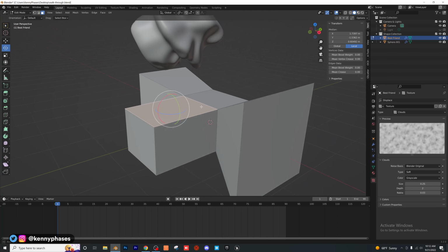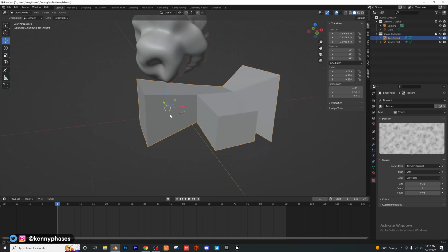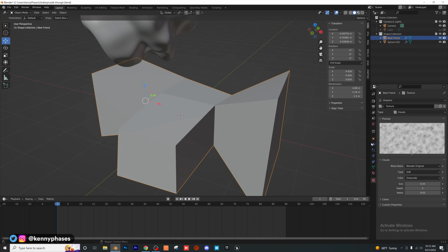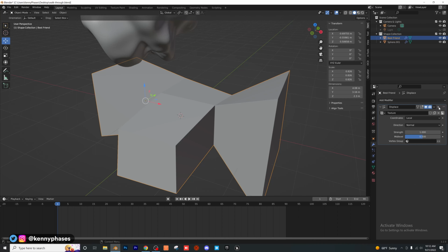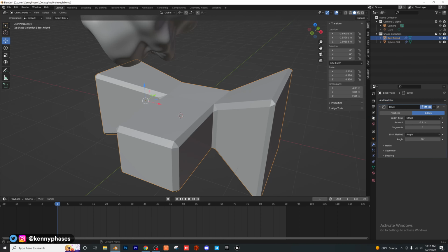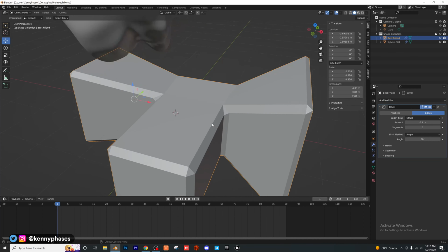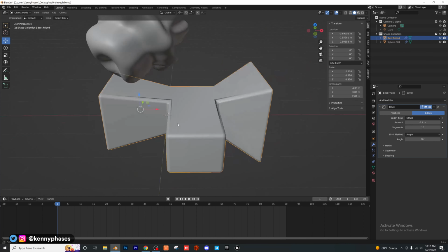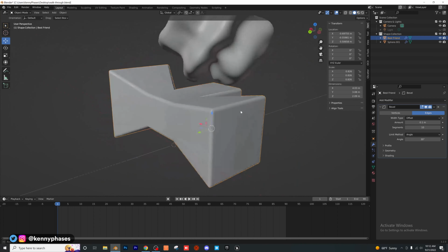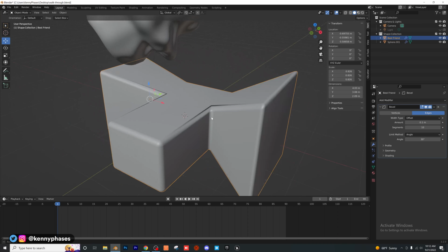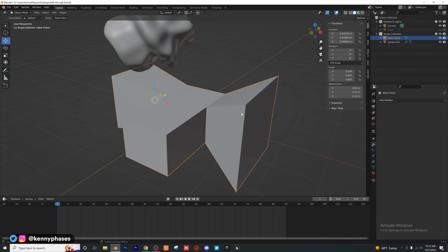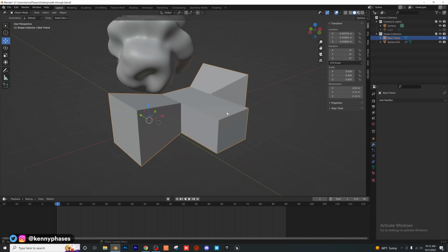Now let's tab out of edit mode, and now we have our newly created object here. Let's say we wanted to make it a little smoother, make all those edges just a little bit smoother. We could go in here, get our displacement modifier out of here, and we could go ahead and create a bevel modifier, right? And so it's starting to bevel all those edges, and we would just increase our segments maybe up to 10. And then I'm going to right click and shade smooth. Now we have this nice smooth look to our object. So that's just a quick way to get a quick effect with something you just created. I'm going to turn that off because I don't really like the way that looks, and I'm going to shade this flat again.